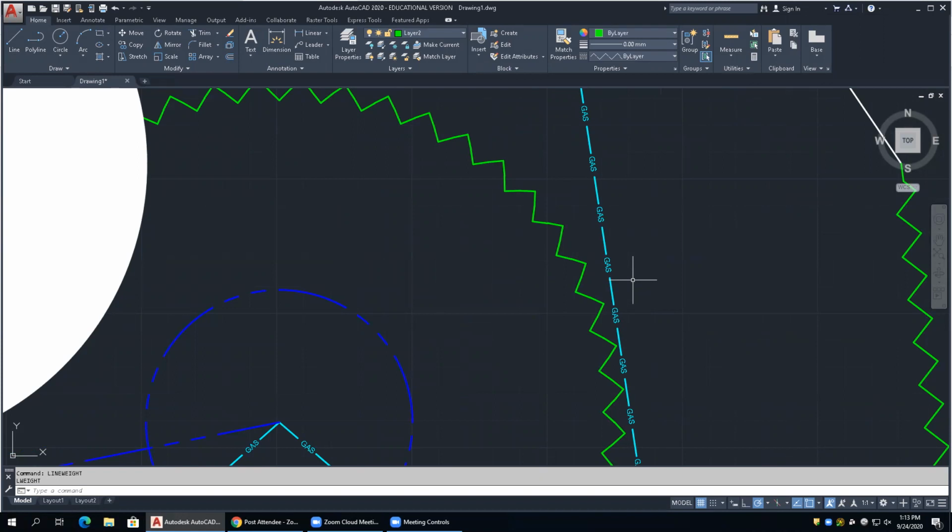I don't like to draw with line weights turned on. So I usually keep them turned off. In fact, I don't typically use line weights that much. I just don't. I usually do pretty much everything with colors and line types. But line weights are another option out there. And for instance, if you want to call attention to something, you make it bolder. So you give it line weight at a certain color and a certain line type, your attention is going to be focused on that. And that's important when you draw, right? So you can adjust your line weights that way.